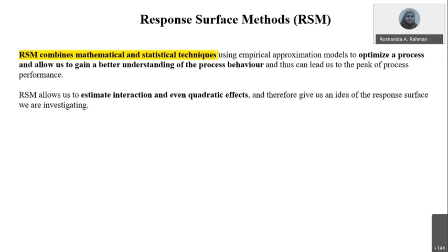By using RSM, you not only understand the process behavior by looking at the single factor as it is, but you also look at the interaction between the factors, and if you can get the higher order model, you can also look into the quadratic effects or higher order model effects. Okay.